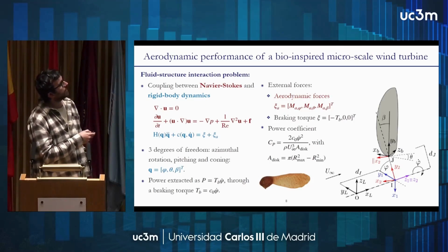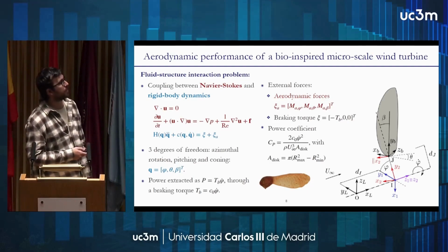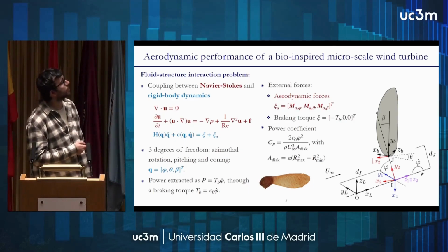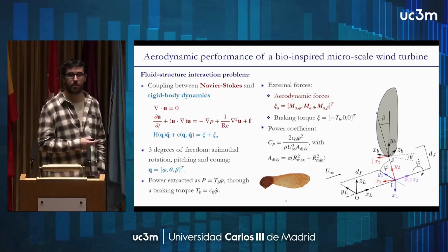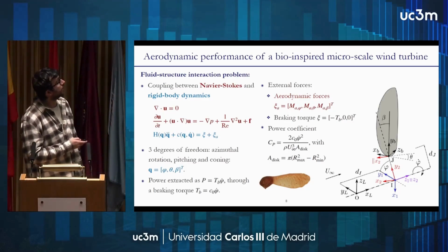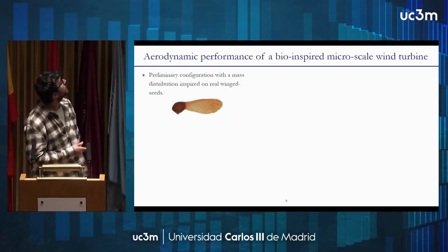And we are going to compute the power coefficient based on this power. Of course, since this couples the fluid and the rigid body dynamics, the aerodynamic forces enter on the right-hand side of our dynamics equation, okay? The same goes for the braking torque, of course.